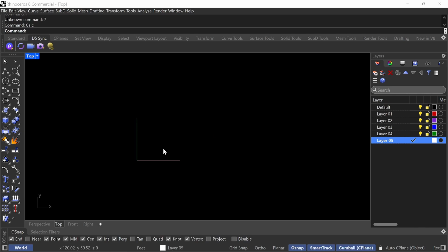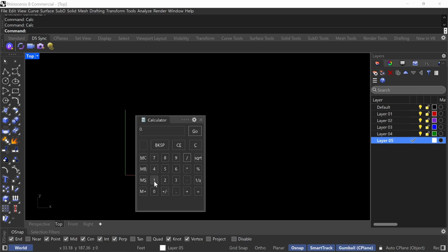So let's say hypothetically we have a floor-to-floor height of 12 feet. In Rhino, there's a calculator you can just use. If you do 12 times 12 to convert it to inches, that's 144 inches. Then you divide it by 7. This tells you how many risers you need. Obviously, you can't have 20.5, so you round up to 21. You need 21 risers.